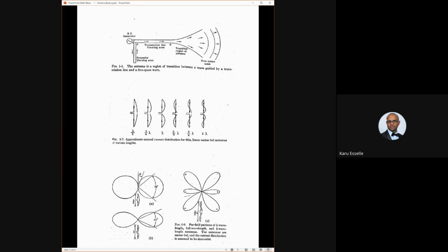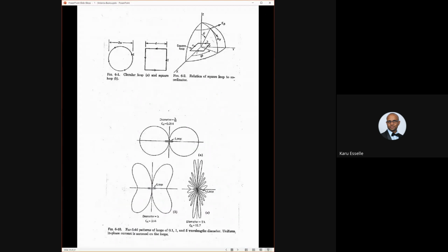So that is like the smallest electric dipole. Likewise, you can create a magnetic dipole, and that is a very small loop. But in practice, very small loops don't radiate very well. So usual loop antennas are made out of, again, conductors with circulating currents. Of course, you have to feed it somewhere, so you have to cut this loop and connect it to a transmission line.